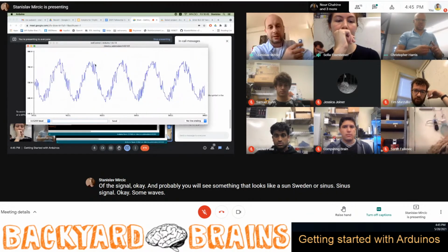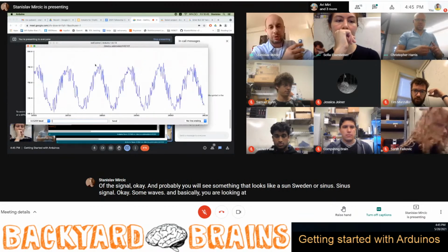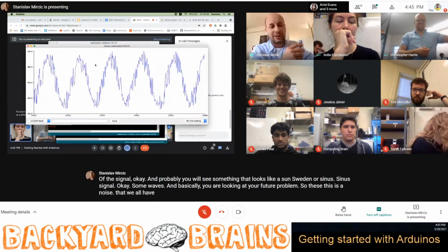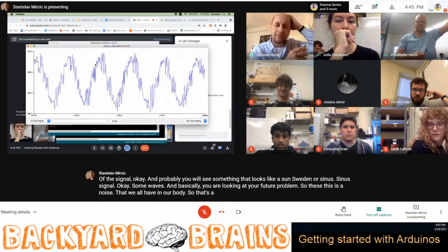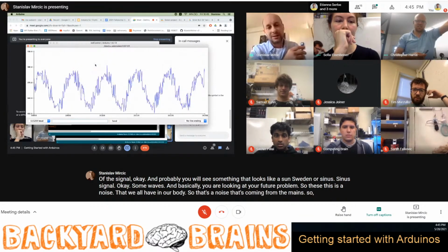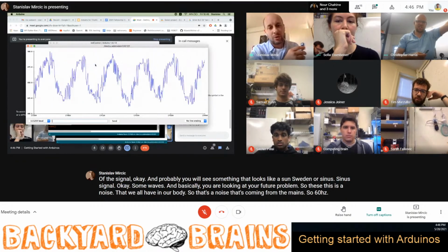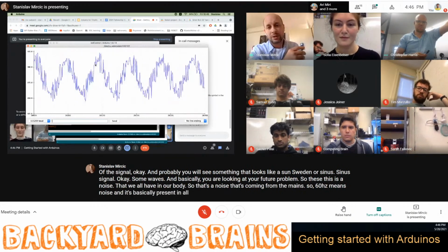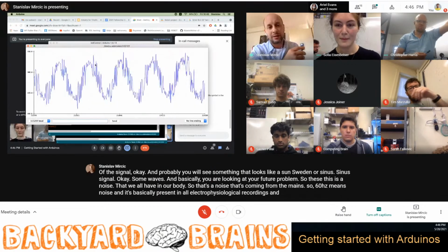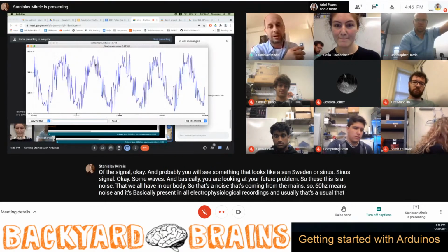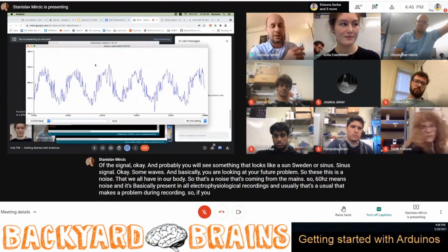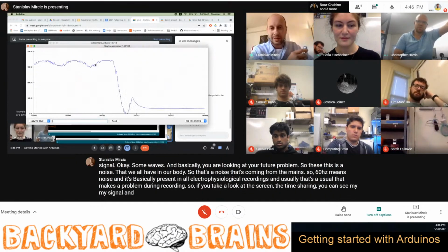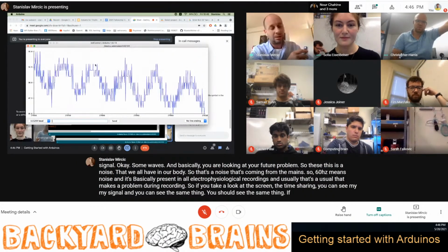Basically, you are looking at your future problem. This is a noise that we all have in our body. It's noise coming from the mains, 60 hertz mains noise, and it's present in all electrophysiological recordings, and usually that makes a problem during recording. If you take a look at the screen that I'm sharing, you can see my signal. You should see the same thing if you touch the pin on your side.